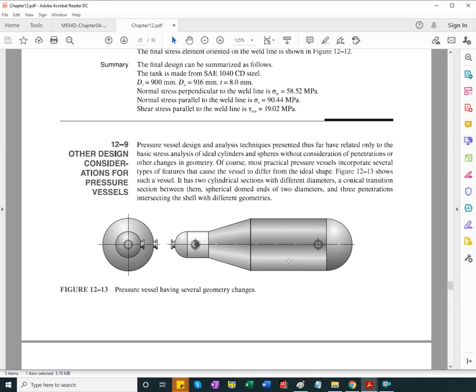For example, hydrogen storage is problematic because it can do hydrogen embrittlement, particularly to higher grade steels, not the softer ones. Oxygen oxidizes the inside surface, and acetylene gets stored dissolved in acetone, and there's a porous material to the inside. So it's an area of study by itself.